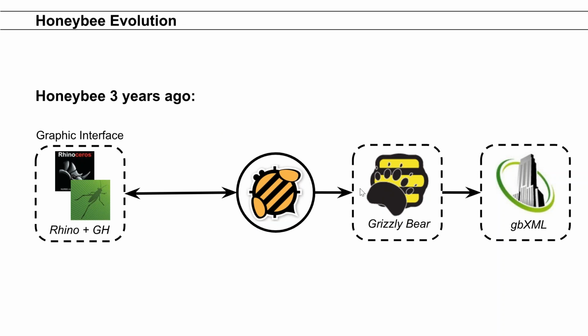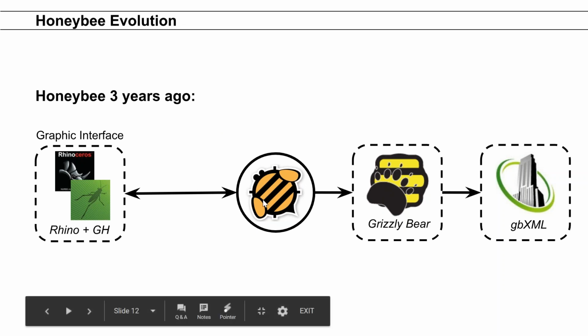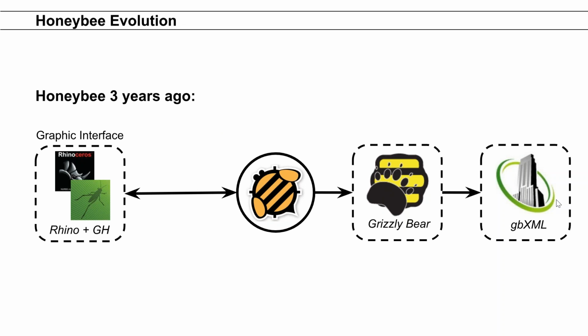And so we had built basically a translator to take all of that info in Honeybee and spit it out into gbXML. But as we were working with this more, we realized, particularly with what Stephen was talking about in the beginning of having validated workflows for gbXML, when we're doing everything ourselves like this, it's hard to maintain it and keep it at the standard that we know is validated. And perhaps most importantly, this was only a one-way street: you can only take an energy model that you built with Honeybee and export it to gbXML.